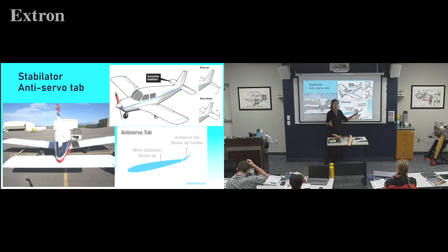It's making it a little bit harder to pull back or push forward because it's deflecting more air down. That keeps pilots from shoving it too fast, too far. So it's helping prevent over-control by the pilot. Why not just make the control heavier through other methods like stronger cables? Probably because this is simpler and cheaper, I'm thinking. Train your pilots to not over-control.